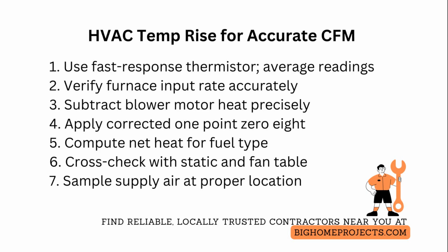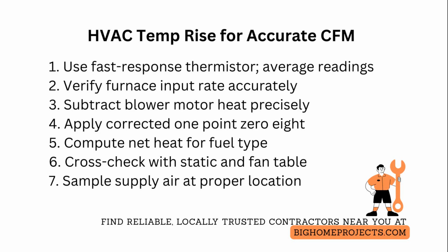Keep supply plenum sampling at least 12 inches downstream of the heat exchanger or electric elements and upstream of any bypass or humidifier injection to avoid mixed air errors.